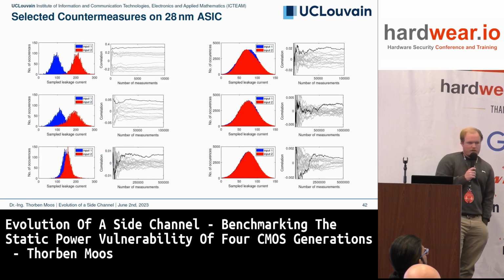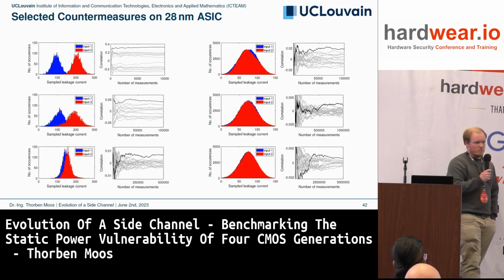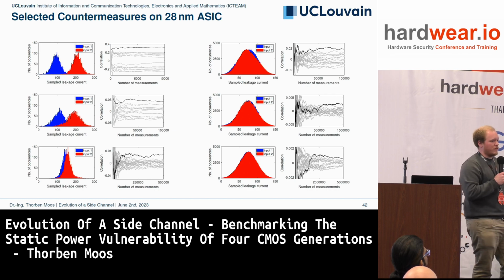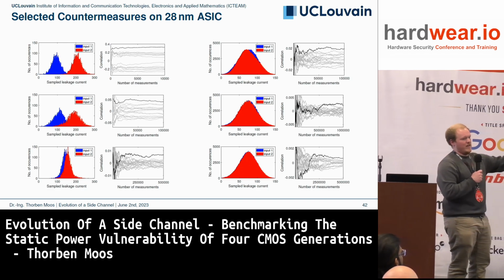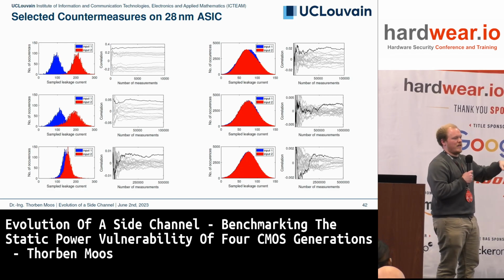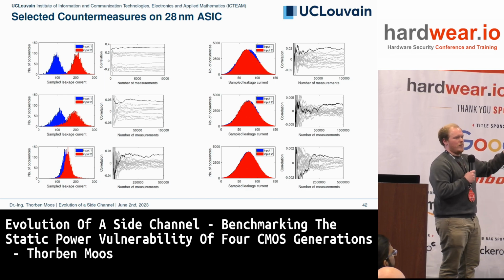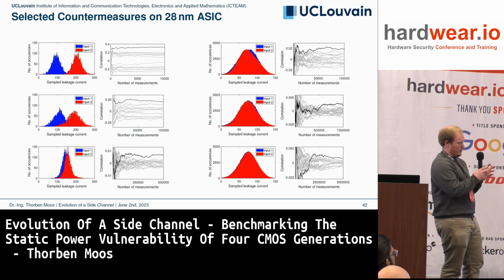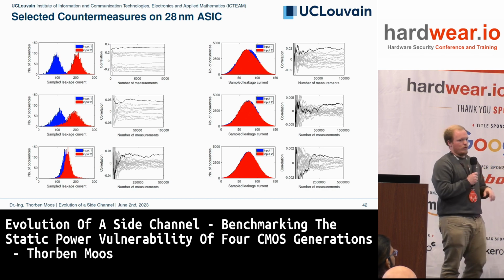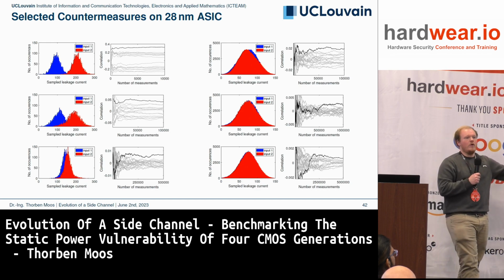These are actually moments correlating DPA, which is a side channel collision attack, where you use part of the traces to model and part of the traces to attack. It's very similar to a template attack if you don't have profiling access to the device. So you do not do profiling in advance. You separate your traces, and then you use one part essentially for profiling without knowing the key, and the other part for the attack.